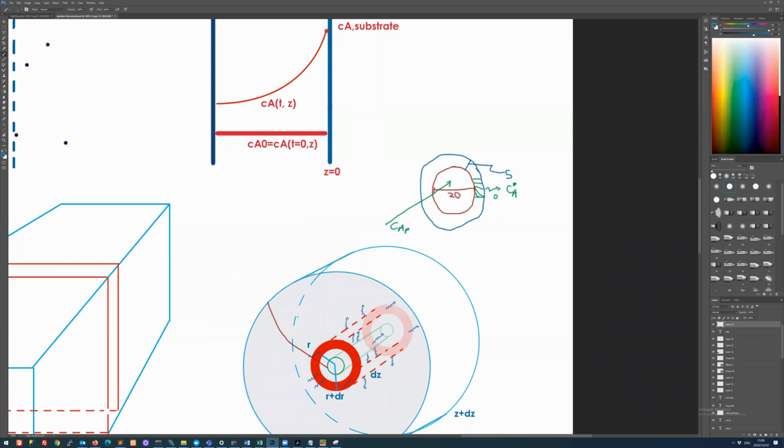So what I'm trying to say is that in the Z direction, we are not concerned that we have significant end effects, right? If you had a short O-ring, let's say the O-ring only looked like this, if it had this appearance, then you can say, well, the area here is not that different to the area here, so we have to be concerned about variations in the Z direction and in the R direction.